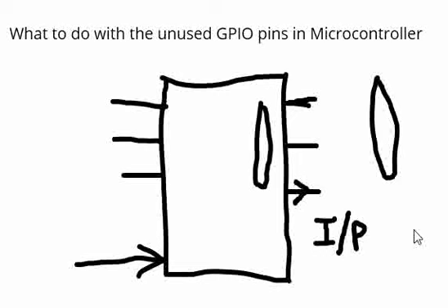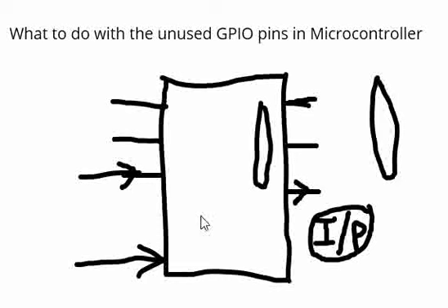Now, in these cases, input pins are very sensitive. So any unused pins are to be configured properly as high or low, else they might pick up noise that is present on your PCB, and this could be an EMI/EMC problem on your board, where the noise could interfere with the chip operation, which might result in an unintended output.